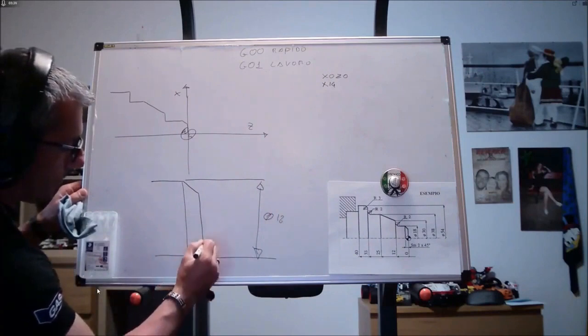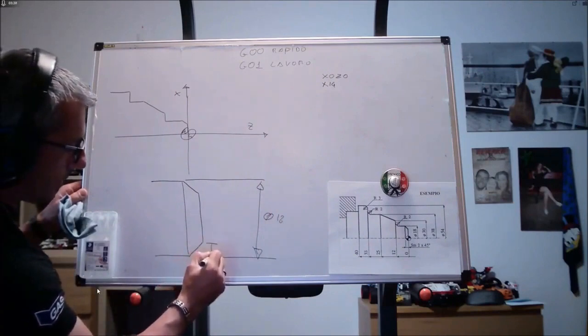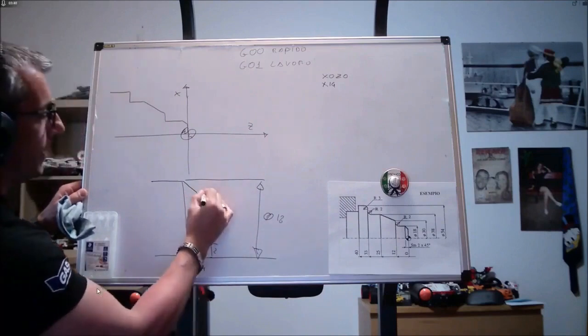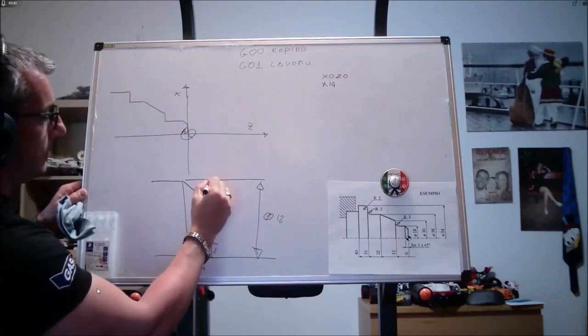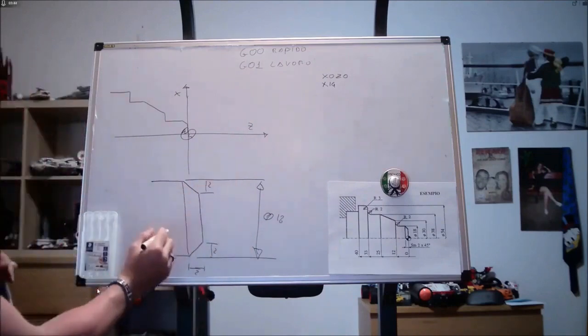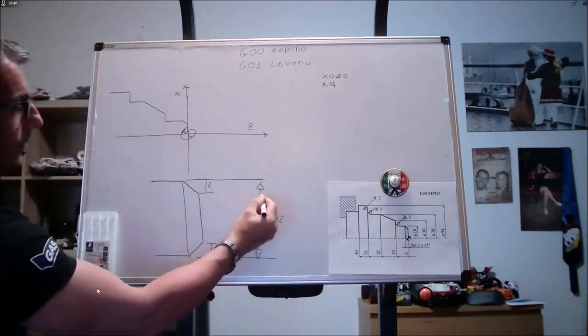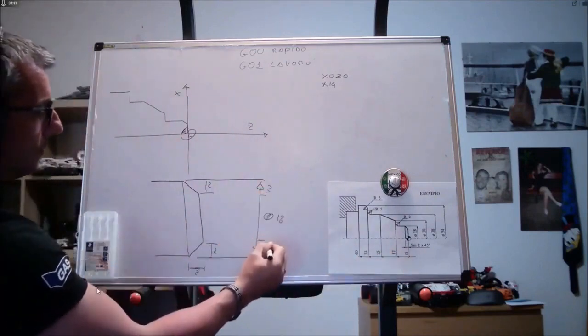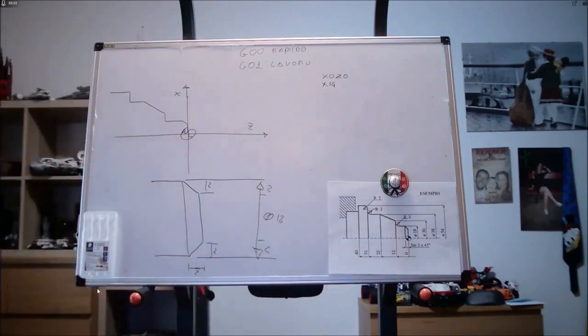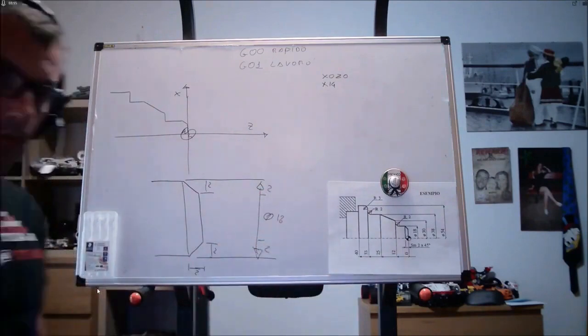This means that 18 minus 2 equals 14 millimeters. The chamfer helps in reducing stress concentration and improving the aesthetic of the piece. It is crucial in ensuring that the piece fits perfectly in its intended assembly, preventing any sharp edges that could cause injury or damage. Diameter.